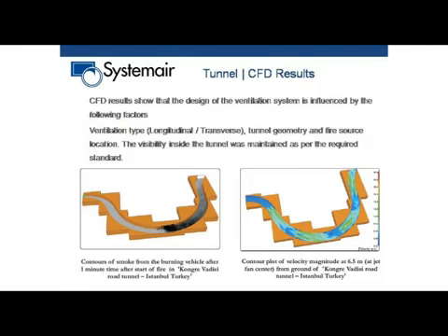This was a particular example for a curved tunnel. And also in a lot of cases we have to make decisions on whether we should use longitudinal ventilation or transverse ventilation to remove the smoke. So all these decisions can be made by using smoke simulations. Here you see velocity contours. These are the fans installed here.